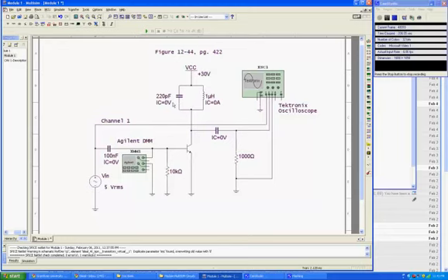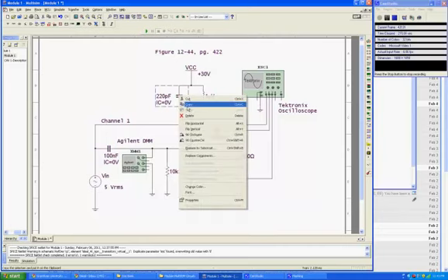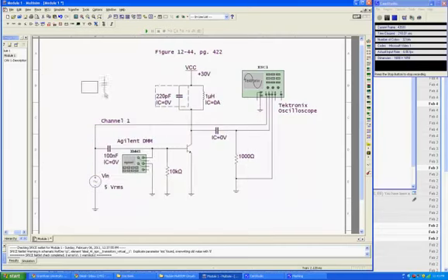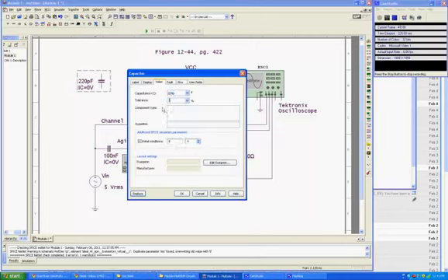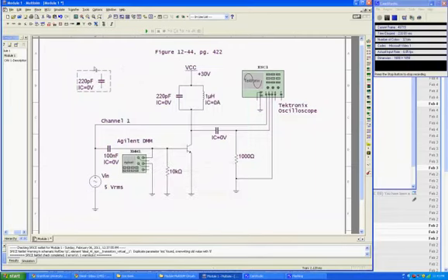Next we have the capacitor. The initial voltage is going to be 0 on that, and it's a 220 picofarad capacitor. I'll show you where to grab one of these capacitors, and then, once they're on the screen, you can right click and copy and then paste, so you don't have to go back to the library again to get the particular component. You can simply make your adjustment, in this case your farad reading. Let me get rid of that one since it's a copy, and again back to our grouping.